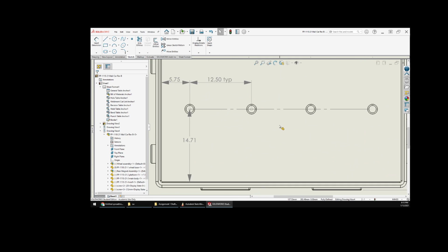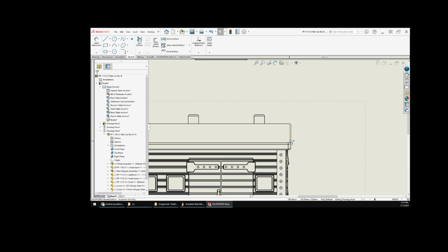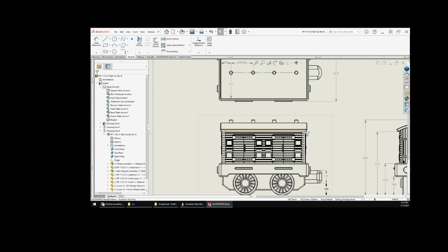For the radii, oh yeah, I would do that on a part, because there's not a consistent radius in here. But if I was to blow out this part, and the radii were all like 0.1, I would do 0.1, point it to one of the radii, and then just call that typical. And what that means is, typical is,